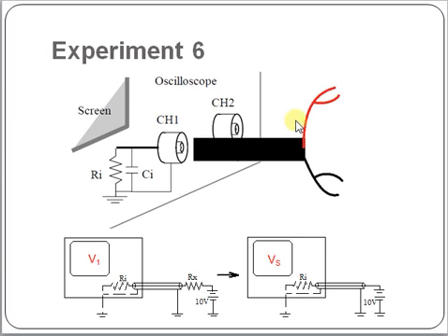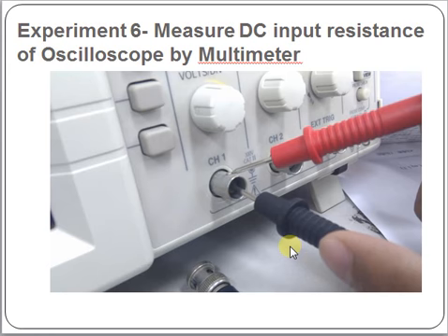The oscilloscope wire has a red end and a black end. The red end will connect to this wire and have to pass the resistance or the capacitor to reach the ground. So we can use this to make the resistance of the oscilloscope become serial with our output resistance. According to the number of divided voltage, you can calculate the resistance of the oscilloscope. While measuring with your multimeter, do it this way.